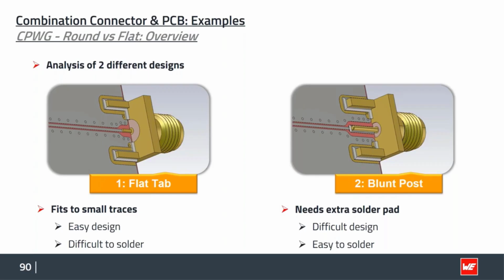So you can see we really start here to completely make a good ground connection on the top side. We compensated the capacitive parasitics brought in by the flat tap by doing here a ground taper structure.